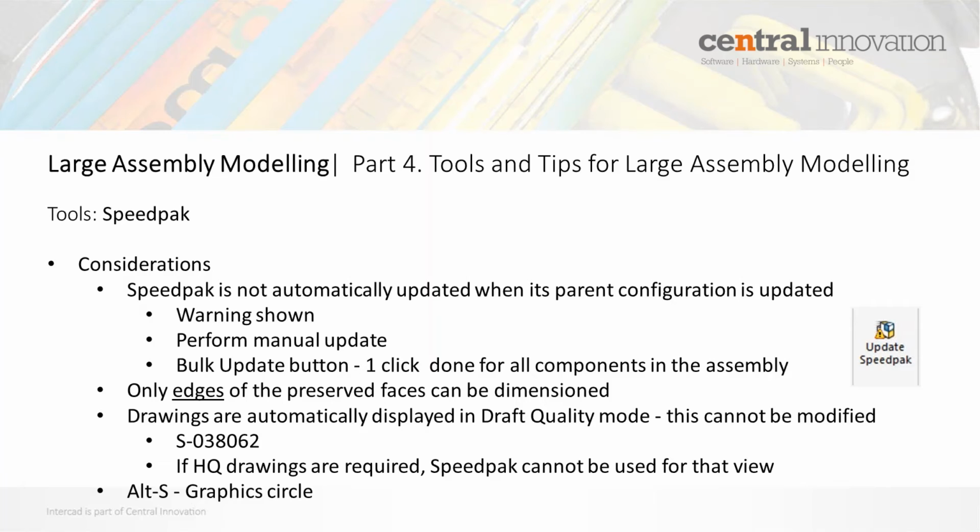And the other consideration here is that drawings are automatically displayed in draft quality mode, and you cannot modify this if you're using SpeedPack. If you require high quality drawings, SpeedPack cannot be used for those specific views, and that usually becomes an issue if you've got to save out to either DXF or PDF, Adobe PDF file formats. When you're exporting to either DXF or PDF, you need to have high quality drawing views. Okay, and I've already mentioned the graphics circle there.